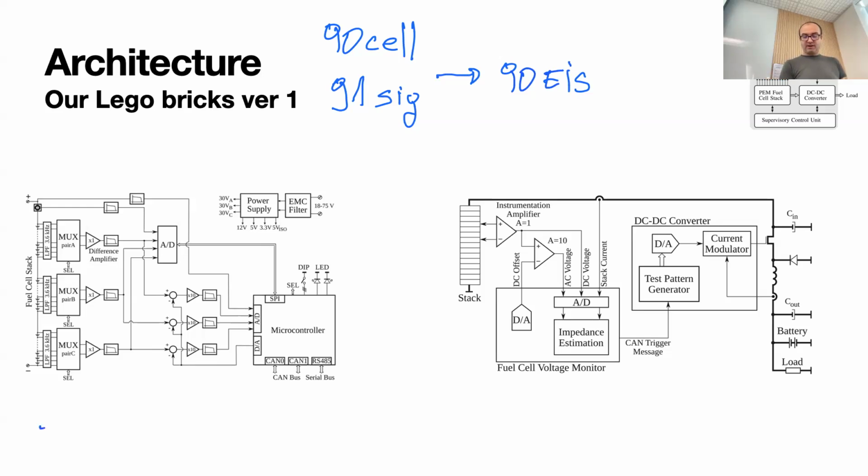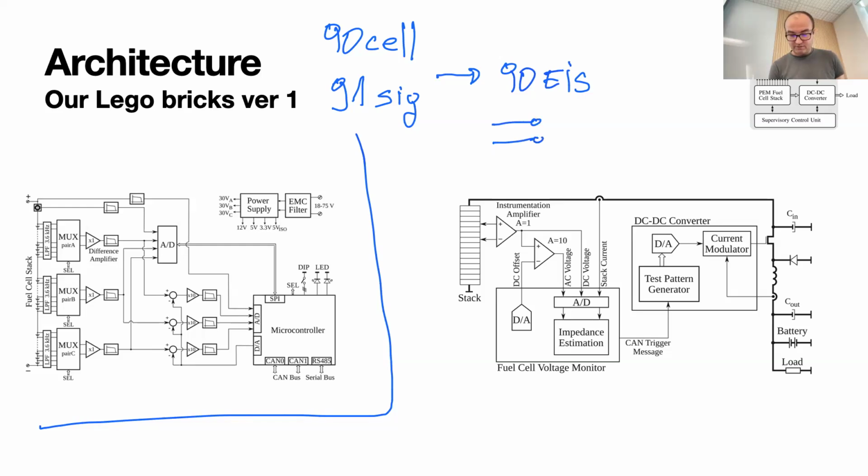So this is the part here. I'm going to explain how it works. This is not an electrical circuit, but a block diagram. Because there are so many channels, measuring them all in parallel is possible, but not within the price range that was required. So what we were doing is measuring really fast, jumping from the first to the last channel, like a multiplexer.